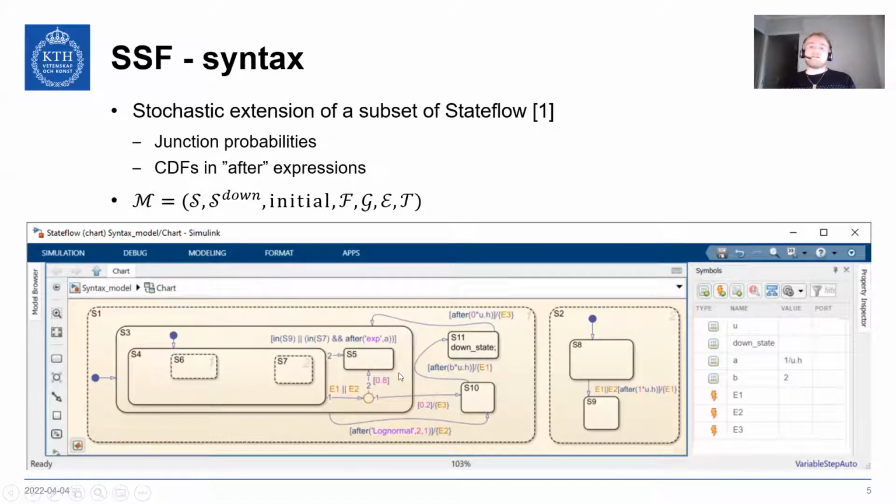All of this is actually one transition, but the transition has two possible destination states. You put the condition events on the arrow into the junction, and you also put the guard here if there are any. Then you put the probability that that destination state is chosen, together with the broadcast events that will be sent, on the arrow outgoing from the junction.